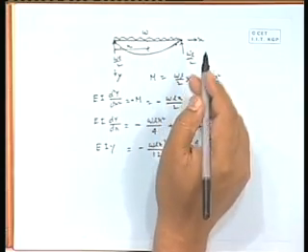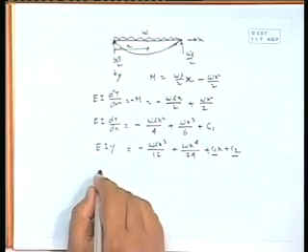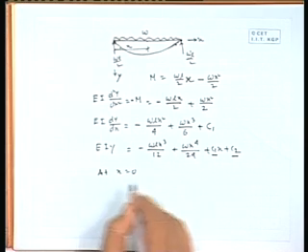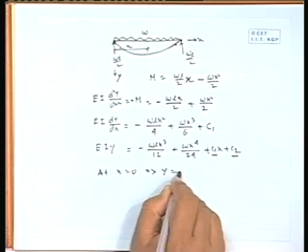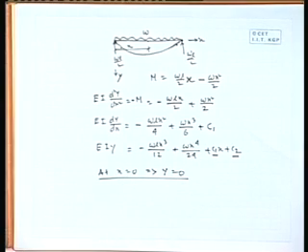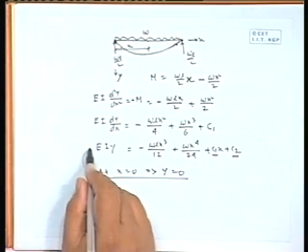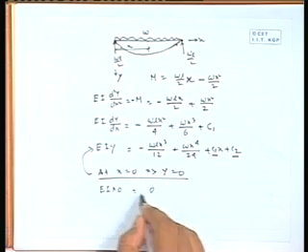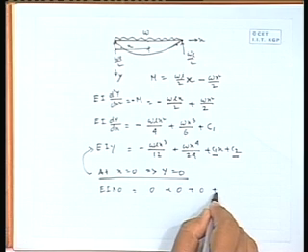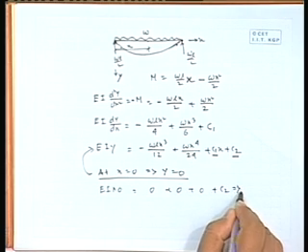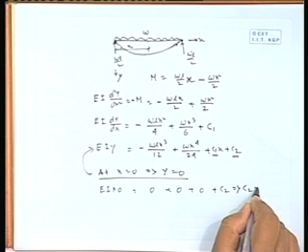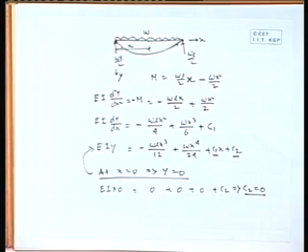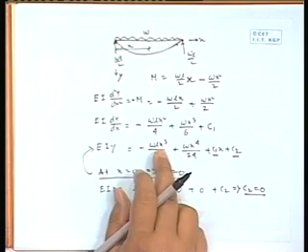So, our boundary condition is at x equal to 0, y equal to 0. This is one of the boundary conditions. So, we can write E I y equal to, this will be 0, this will be 0, this will be 0, and C2, and that will lead to C2 equal to 0, because everywhere it is multiplied by x, x cube, x to the power 4, x.